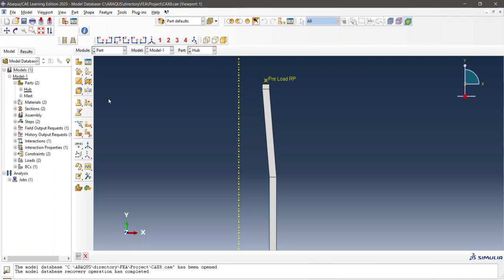So this is the hub. The hub I'm using is aluminum. This is not what you would find in that aircraft, but it's a great substitution. The hub uses a composite material, and I wasn't super familiar with applying that material in Abaqus or with getting information on layering. So aluminum was a great substitution. It's used in other hubs in rotary aircraft.